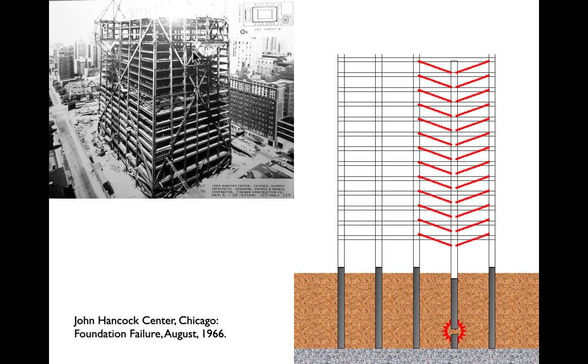Not to mention that even if the column survived or the caisson survived, all of those slanted floors would have to get either certainly replaced, and they might not be serviceable, right? There might be a greater slope than we could stand to make the building work. So construction stops for 6 months. They investigate what's happened by taking sample cores, drilling into every one of the caissons, and confirming that the caisson is either solid all the way through or not.